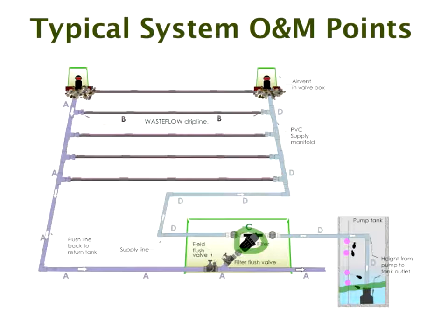Their urine carries the chemical through into the septic tank and kills the bacteria. And we have an upset. That is quite a common problem. Not very common, but quite a common problem. So that can be a question to ask if you're having a system that's persistently giving trouble.